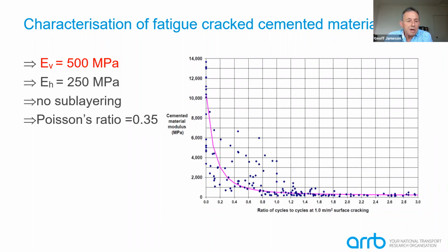So this might be a situation, say, where you have 200 millimeters of asphalt overlying a cement treated material that's used as a subbase. If that cemented material cracks, there's still some usable life left in that pavement as far as the road user is concerned. It still performs okay. That cracking wouldn't come through to the surface, and there's some usable life left after that.